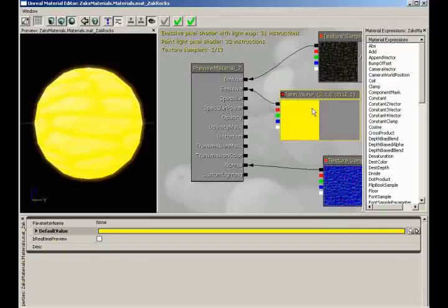For example, I could have a texture, and I'm reaching here, and you got to kind of conceptualize in your head with me, so bear with me. We could have a texture that looked like a checkerboard, black and white checkers, okay? We could multiply this yellow color by that checkerboard. What would that actually do? Now, I'm not going to do it here because we don't have a checkerboard texture, and I'm not going to create one just for the video. It seems to me like every place there's black, that's a value of 0, as we've already seen. So if you were to multiply the yellow RGB color by an RGB color of 0, 0, 0, you would end up with a result of 0. That's right. Means that particular area would not be emissive. You'd have yellow glowing checkers and then areas that weren't glowing. That's right. That would be your overall result.